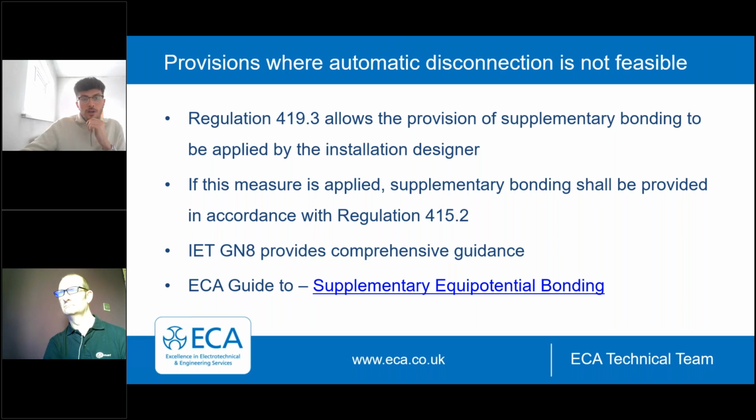If this measure was applied, then we would need to apply it in accordance with regulation 415.2. The IET guidance note 8 gives comprehensive guidance around this. So we encourage you, if you're looking at using this measure, it's an option often missed, so it's just a raise of awareness on that. We encourage you to consult the guidance within guidance note 8. And ECA also has a guide available to members for supplementary bonding.